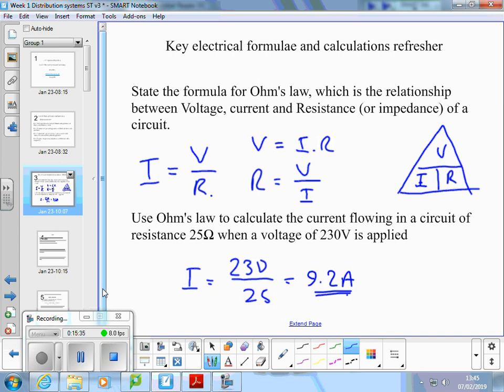All right. The other thing I'm quite hot on is if people say they're looking at a circuit and they say there's 25 volts going through that resistor. Current goes through, voltage is applied across. And that's about knowing those basic principles of what the current is. That's a measure of how much electrical current's flowing. Voltage is like the pressure you apply in a hydraulic circuit. It's what forces the current through.